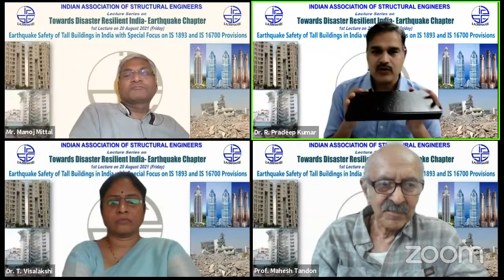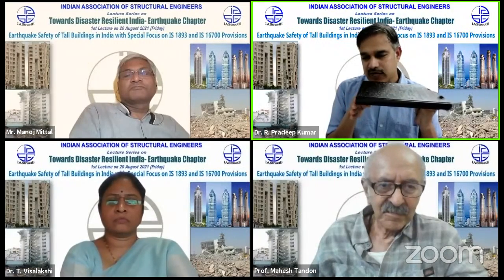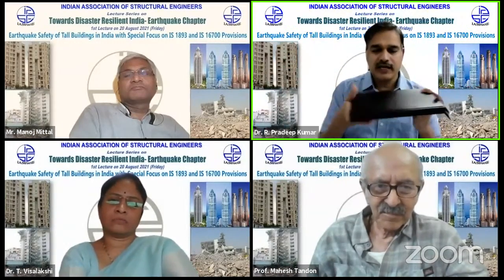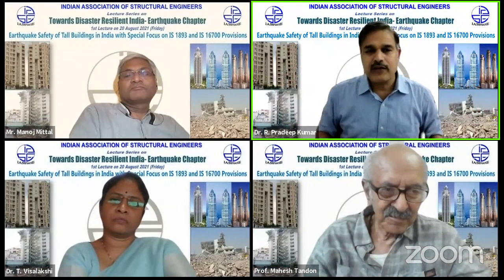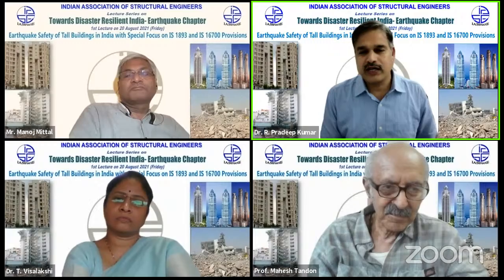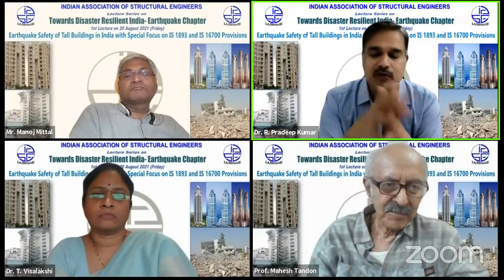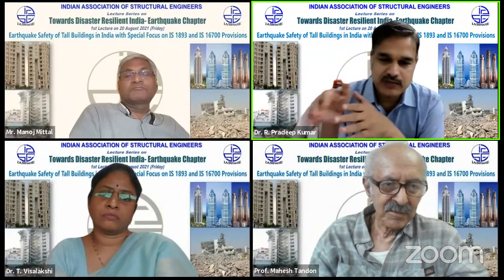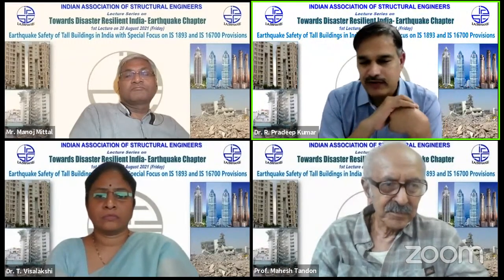Usually it is good to distribute lateral load to the resisting elements in proportion to their relative stiffness. But if the aspect ratio is very long, the floor tends to bend in its own plane, so the central lateral load resisting elements take more displacement compared to the edges. So that is rigid floor and flexible floor. In a rigid floor, distribution is proportional to relative stiffness. In a flexible floor, distribution is proportional to tributary area, and that is not advisable. Rigid floor diaphragm action is advisable.